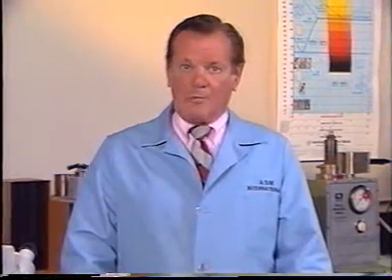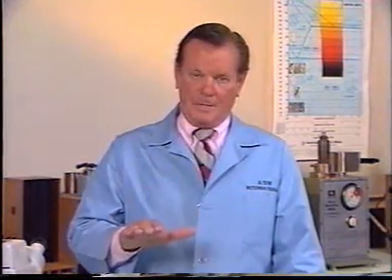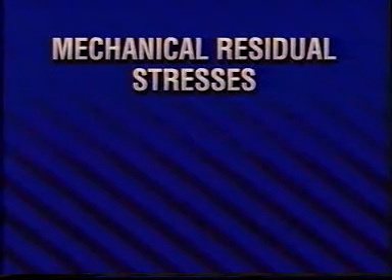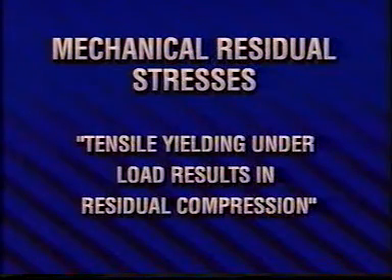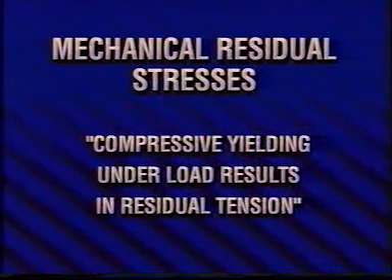For best fatigue performance in most cases, compressive residual stresses are desirable on the surface. The basic principles for mechanical residual stresses are: tensile yielding under load results in residual compression when the load is removed, and the reverse. Compressive yielding under load results in residual tension when the load is removed.